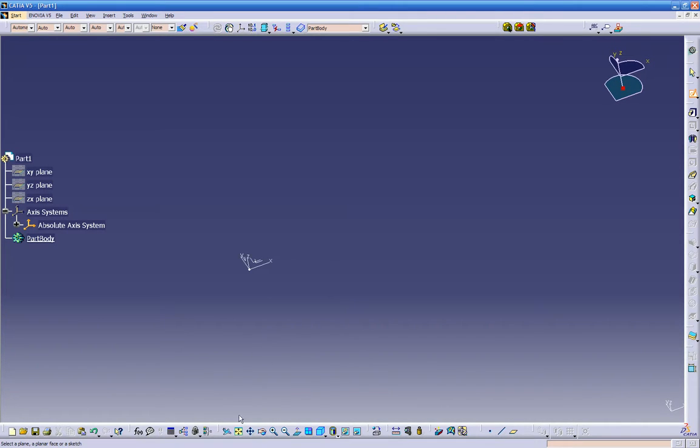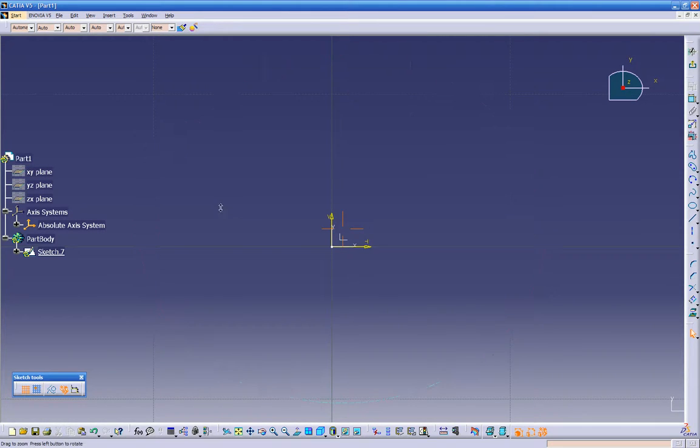So we can click on one of those planes. We can click on XY over here, XY plane. We can see it on the top right here. So if we click on the Z, it's putting our part on XY plane. Or we can click on XY plane up here, which is the same thing. Now we're back on the sketch. And let's create another rectangular. Let's go here.